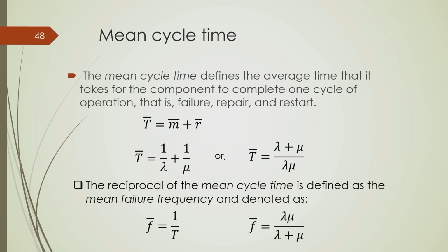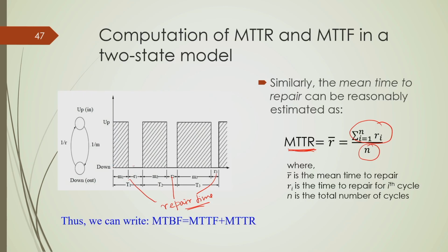Okay. And as I said, for the mean time between failures, here you can see this is one particular point where there is a failure, then this is the duration of repair, and then up to this time the system will operate satisfactorily. So, this is the mean time between two successive failures. You can look at these dots where faults occur, or where we need maintenance for this particular equipment. These represent the times of failure, which basically necessitate the repair of that particular equipment.